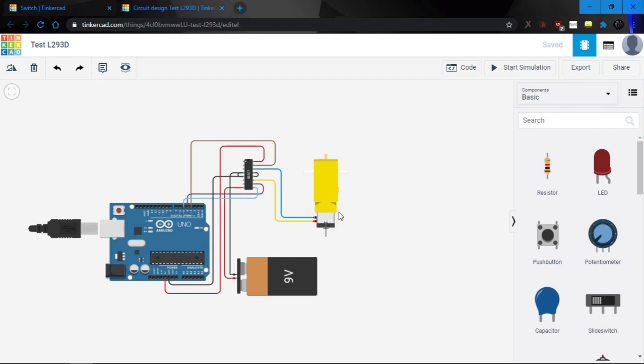And then the second issue is, if you use a lot of motors and share the power source of the Arduino, it will be hard for the Arduino to work, and sometimes it will force the Arduino to restart the board. So if you're doing any wireless project like Bluetooth or PS2 or any other wireless, it will be disconnected and then reconnected, and this will be a problem for you.